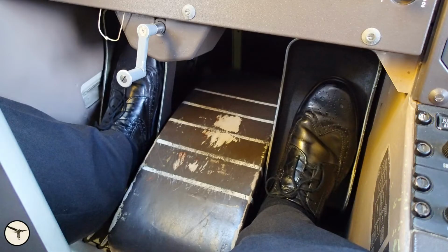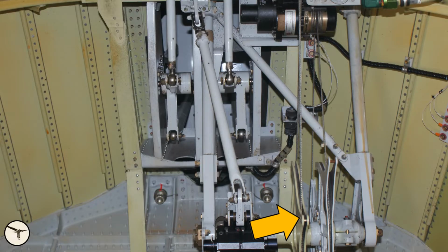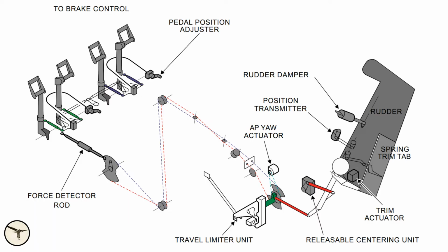The rudder is controlled with the rudder pedals. The pedals are interconnected and there is one pair of cables to the tail section, where the cables are attached to the respective bell cranks. From there, the movement is transferred to the rudder with a control rod.